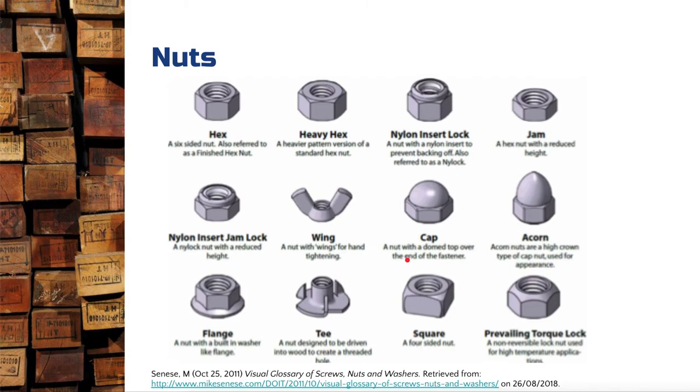Now, the nylon nuts work very similar to the hex, but they've just got a little bit of nylon in it that actually stops them from automatically unscrewing. Really useful in vibrating circumstances. So, for example, I'm thinking about my clothesline outside. When I put my clothes on, there's weight on it, so the bolt actually moves up and down a little bit as I'm taking on, taking off. Eventually, the hex nut might naturally just unscrew a little bit and come a little bit loose. The nylon nuts, they don't back off. Okay, so they stay locked in to the original position that you put them in without any stress.